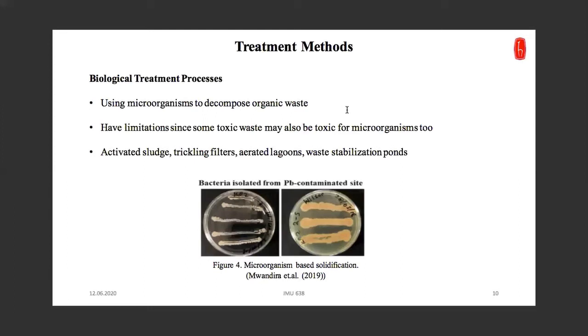Also, you can use microbial induced calcite precipitation bacteria. You can see figure 4. It is a brand new article. I just found it, and it's showing that the first part is the bacteria before the treatment, and the second part shows the bacteria covered by the lead material. So it says that solidification is successful in that kind of organism, because it just collected all the lead around it, and it solidified and stabilized that around it. But it also has some drawbacks: the cost and labor-intensive work.